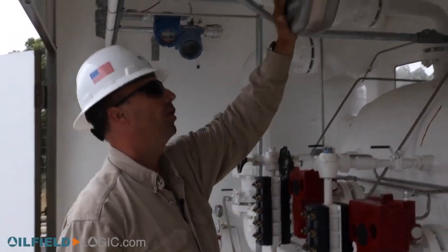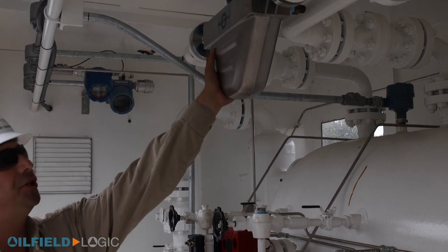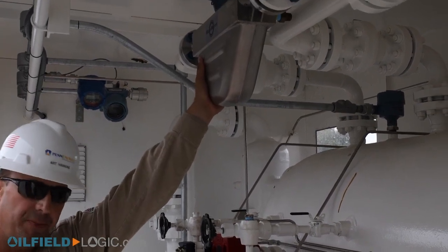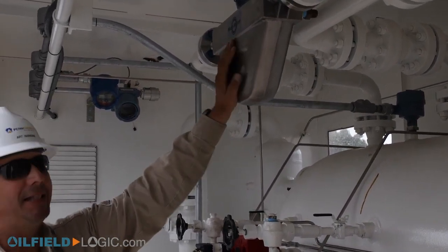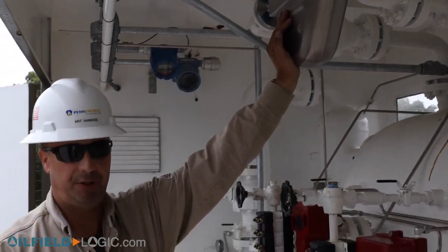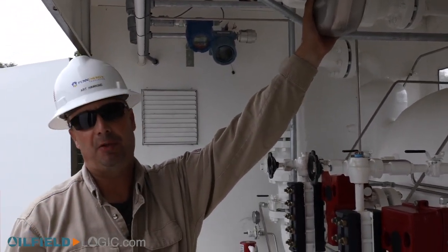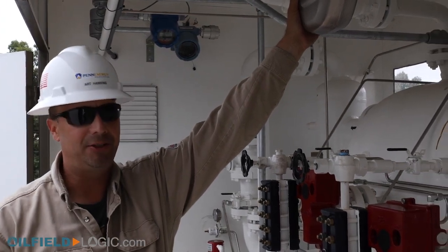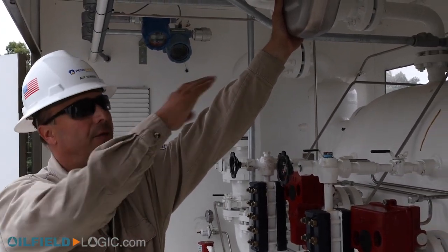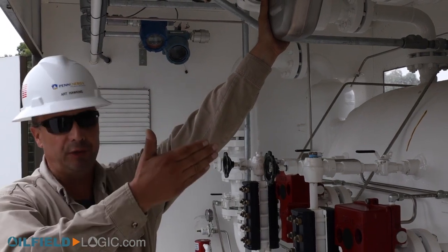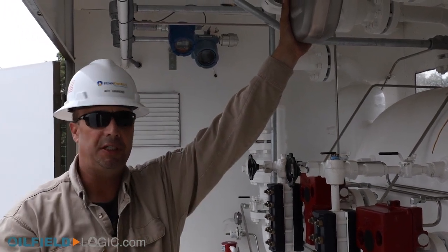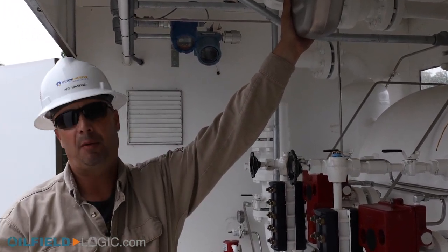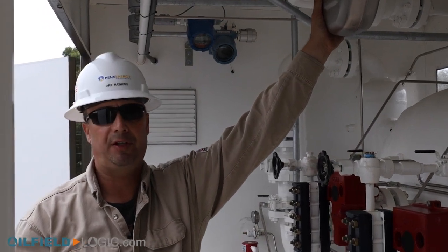As far as the oil or condensate, we measure that by a device called a Coriolis meter. This is measuring density, which is an old school kind of measurement. They use these in cement plants, drains. There's just tubes in there. Flow through the tubes creates a frequency, sends a signal to a PLC, and through some calculations, we come up with the amount of production that we're moving through there.